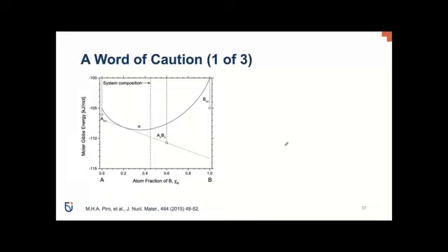So imagine, you may recall at the beginning of the lecture, I gave an example of how the molar Gibbs energy plots can be a graphical interpretation of your equilibrium state. So more specifically, if one were to draw the lowest common tangent between phases, whereby the system composition is in between them, you can use that as a graphical interpretation of what phases will be stable at equilibrium.